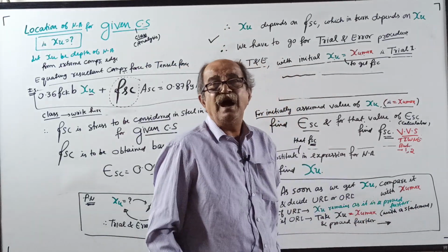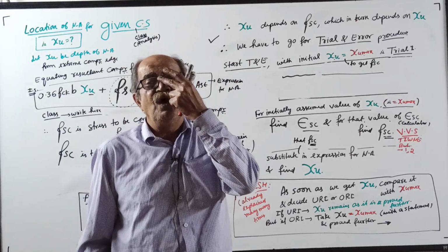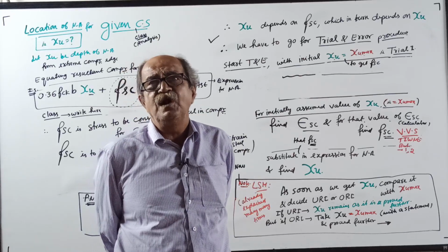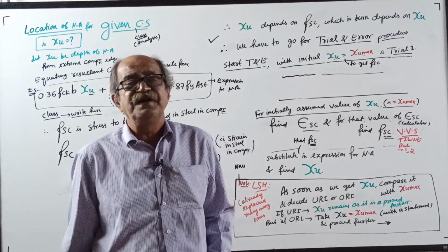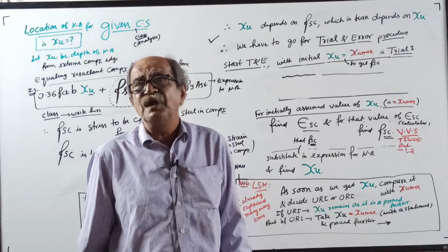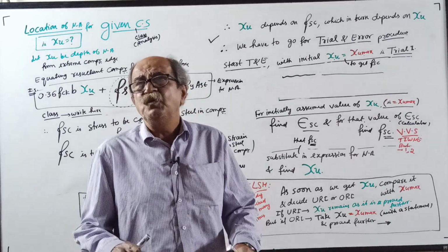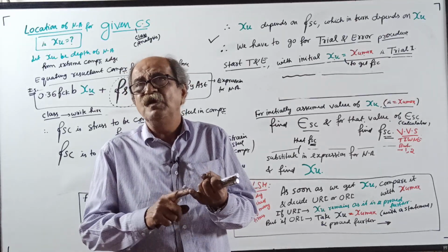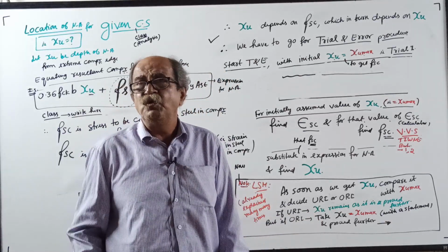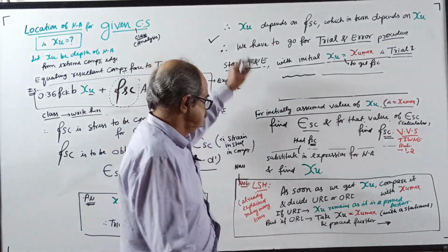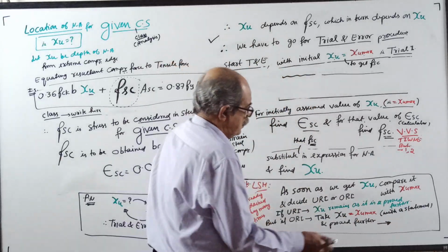I have given the statement for you earlier. In case of analysis, ultimate MR or strength of an over reinforced section is restricted to that of a limiting value balanced section. So if you get xu more than xu maximum in an analysis problem, that more is cancelled. We take equal. Once again, less means less, equal means equal, but more also means equal. When I do a problem and get over reinforced, once I will write it with the statement and proceed further.